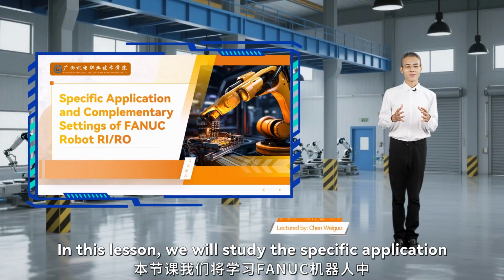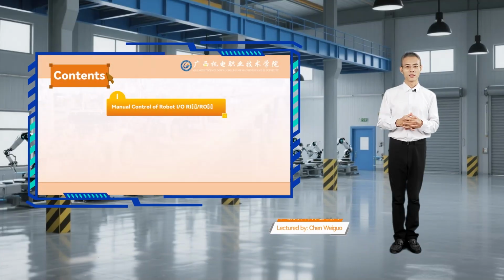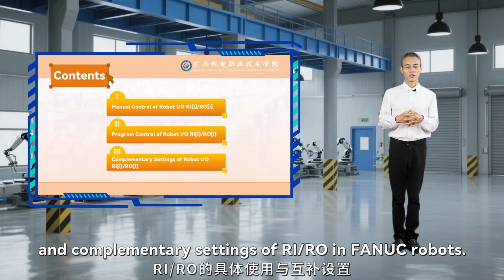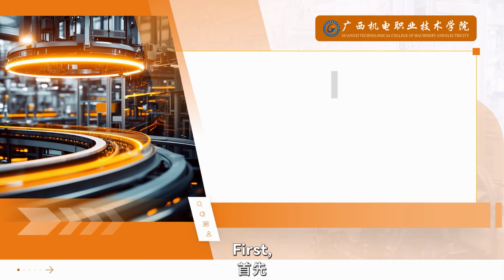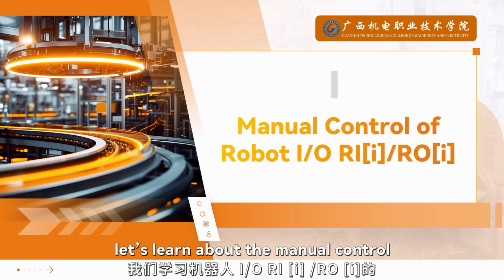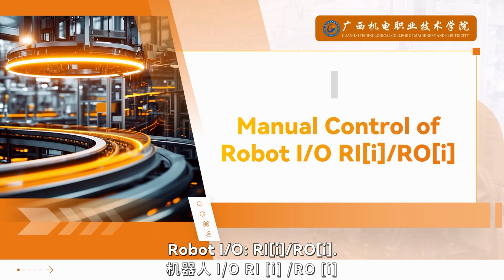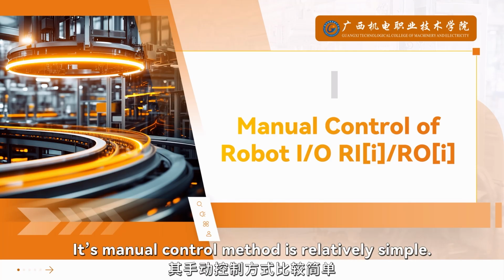Hello everyone! In this lesson, we'll study the specific application and complementary settings of RI/RO in FANUC robots. First, let's learn about the menu control of our robot I/O RI/RO. Robot I/O RI/RO is a manual control method. It's relatively simple.